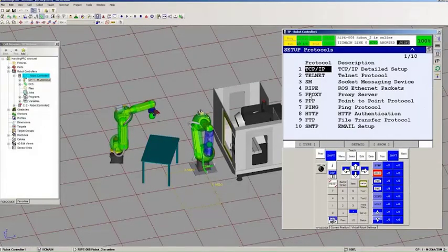Yeah, the question is what does it mean by the hand model? It's the safety bubble around the robot's hand, the safety bubble around the tool. So you're designing your own model to encompass the tool, so that way it's protected before the tool hits something.